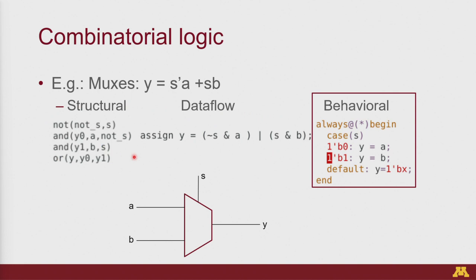So we just define it as a high-level abstraction. The simplest thing in a multiplexer is a case statement for each of the values of the select line. What happens if the value is 0, and what happens if the value is 1. If the value is 0, your output is going to be A. If the value is 1, your output is going to be B.